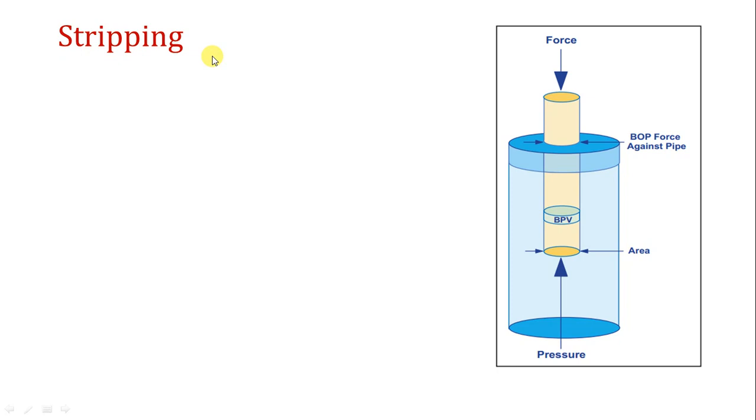While stripping, it is volume balance. It is not pressure balance, but it is volume balance. So once you run in hole here, all the volume of the closed end tubing or closed end drill pipe is compensated or is bled. So for example, if one stand equals half a barrel, then once you run two stands, you have to bleed one barrel through that choke line.